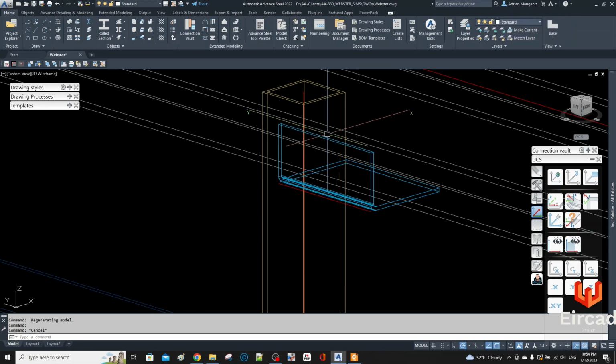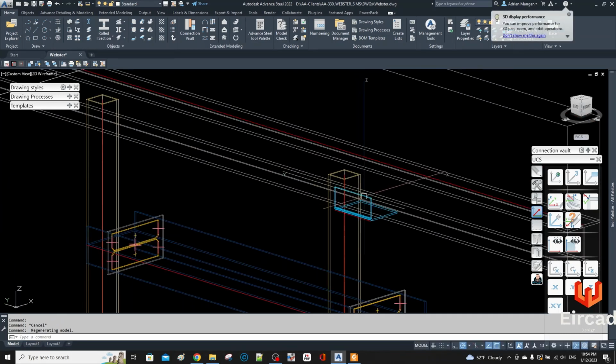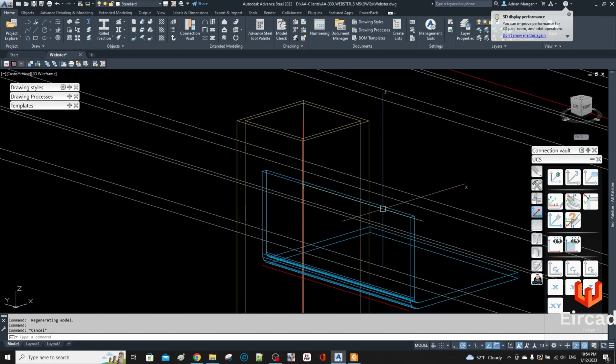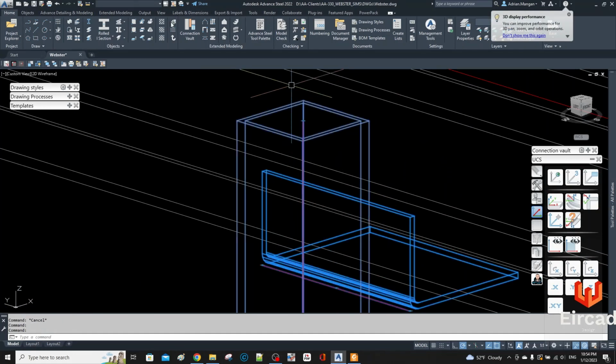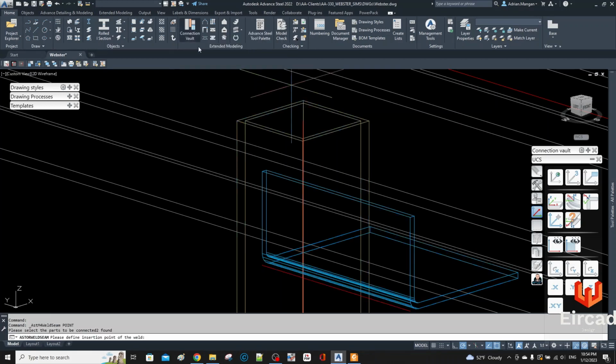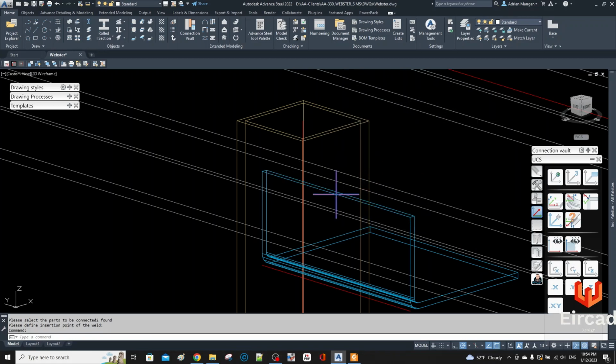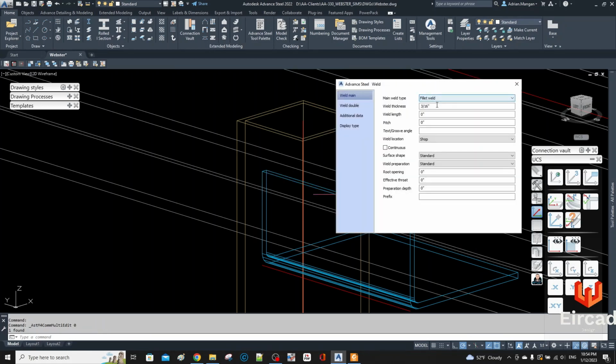I don't need to put in the weld symbol because I'll probably just add it anyway. So we'll put it in, I suppose. So it's going to be a fillet weld on the top. I'm just going to have them welded in 2 places. So it did go in the right place. Alright, I want a fillet weld on the top, so that's fine, 3/16.